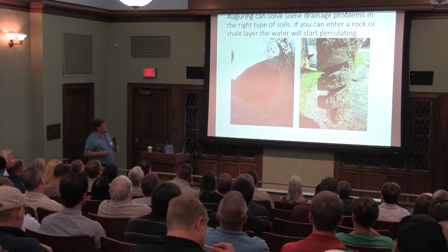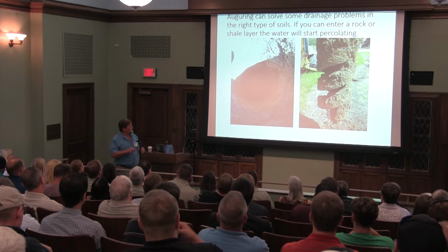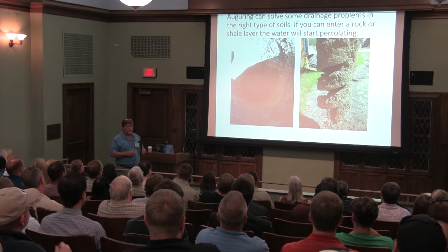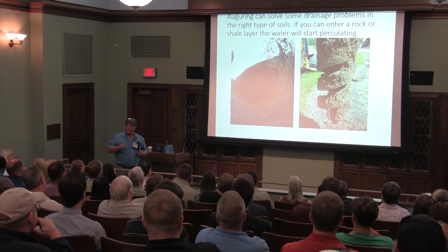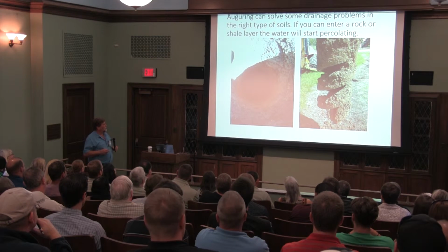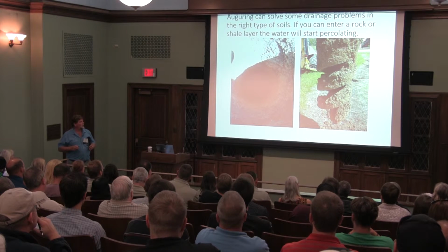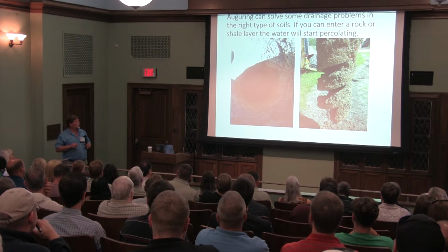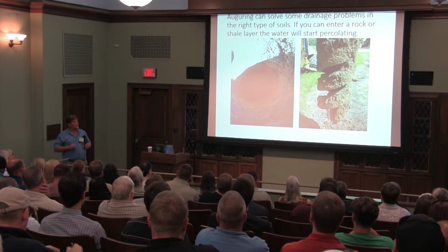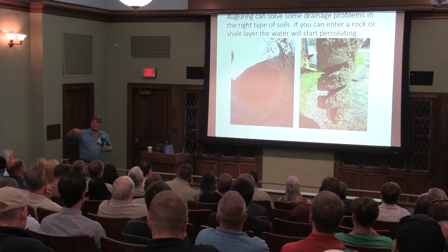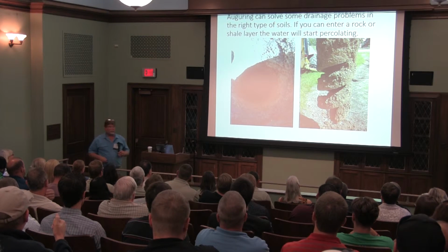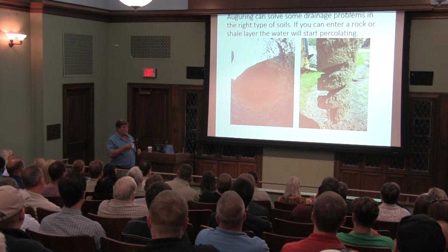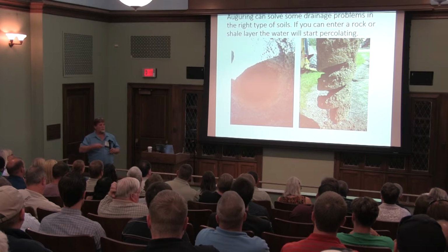So on that particular project, we had multiple. Here's another one. You can see where the grass died. It infiltrated, but it infiltrated very slowly. So the solution I used, and I got in a nice fight with the engineer on this, but I've done this a number of times and it does work, is we have very large augers that we use to set light pole bases in parking lots. We augered these rain gardens, these we call retentive grading areas.